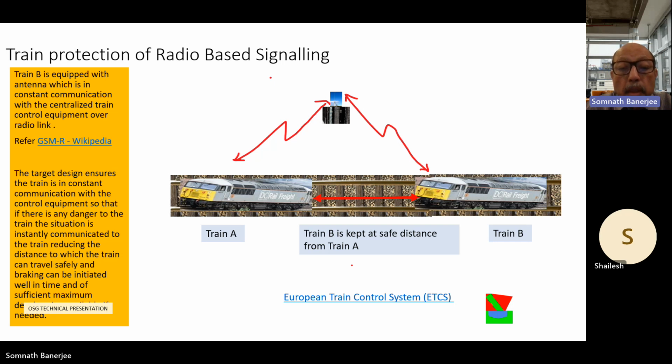This distance is not 100% accurate because the important item it relies upon is the odometer. The odometer on the train will never reflect the true distance traveled, because the odometer is based on the number of turns the wheels undergo, and if there are any slips and unideal movement, that is the train moves but the wheel does not move as much, the errors will be there.